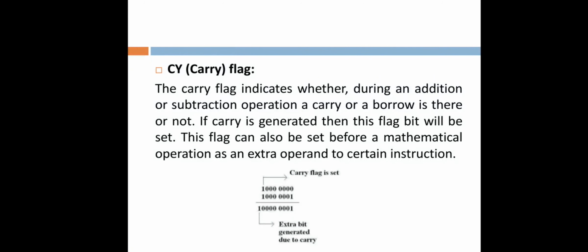Carry flag. The carry flag indicates that during an addition or subtraction operation a carry or borrow is generated; if a carry is generated, then the flag will be set. The flag can also be set by certain instructions, as shown in the figure. When we do the addition, observe the last bit: both are 1 and 1, so the sum becomes 0 and a carry is generated. That's why the carry flag is set.